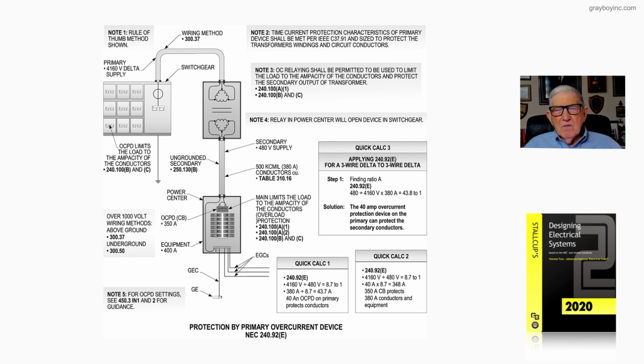Now, we know that new Article 311 covers medium voltage, Article 328 has tables sizing cables, conductors and raceways and so forth. But to get the components in a high voltage switchgear, which you see to the left of the illustration at the top, you go to Article 490 to build your protective scheme, using circuit breakers, fuses, and selecting a switchgear, panelboard, and so forth. When I say panelboard, you know, switchboard.